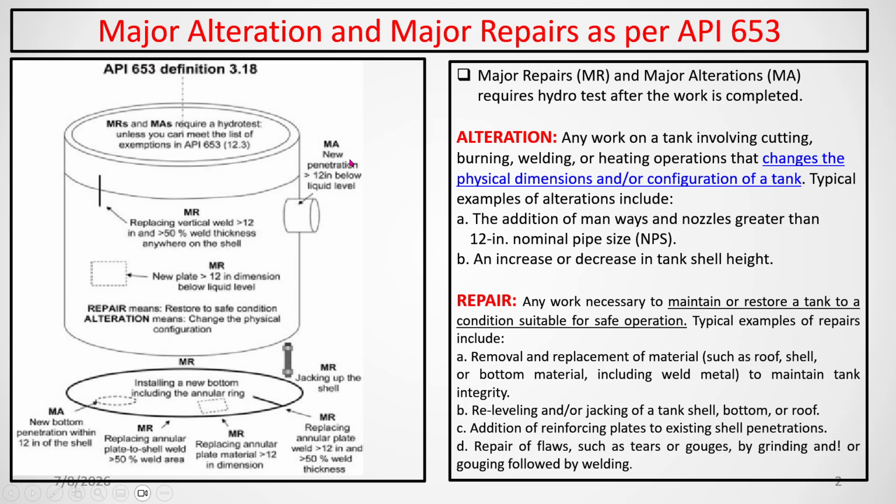Major alteration means a new penetration greater than 12 inch below the liquid level. This is the liquid level. So if there is any penetration more than 12 inch below the liquid level, then you have to go for major. That one is called the major alteration.